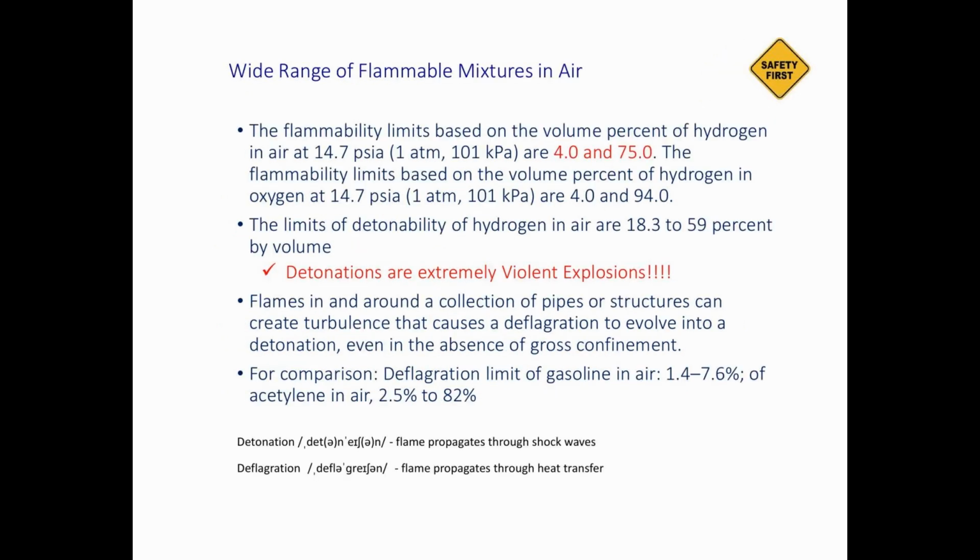The flammable limit is between 4 to 75%. If it's not in air but in oxygen, the UEL increases to 94%, giving you an even wider range. So when you check the LEL and UEL, you need to know the matrix. Sometimes it tells you it's in air, sometimes it tells you it's in oxygen. So the table is different.